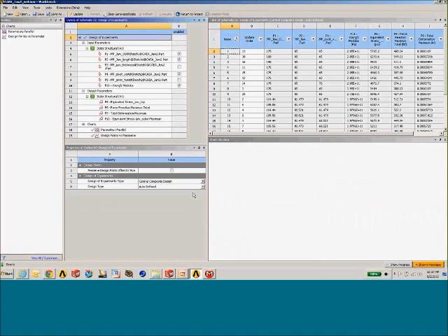Under the Design of Experiments page, we have a couple of different ways that we can set up our DOE matrix. We can use one of the default models like the central composite design, or if you happen to have your design point solutions already generated, either in the parameter set or if they came from the correlation study, you can import those directly, so there's no need to resolve those particular design points. And that would be a custom or a custom DOE plus some sampling. You can add additional sampling points to improve the quality of your curve fit.